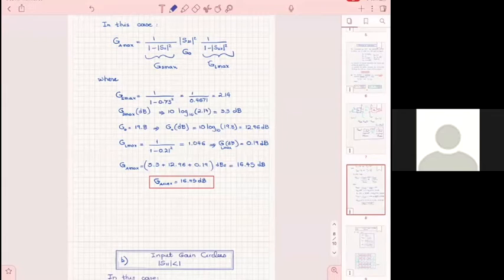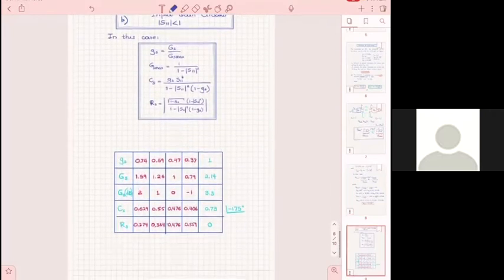There is a trade-off for these people who design transistors, between low noise, F minimum, and maximum gain, GA maximum. You cannot lower F minimum very much and increase G max very much at the same time. So when you have a G max that is very high, you expect that transistor to give a modest noise, not very low, in other words. So that's what we found for this. Any questions before we go to the next?